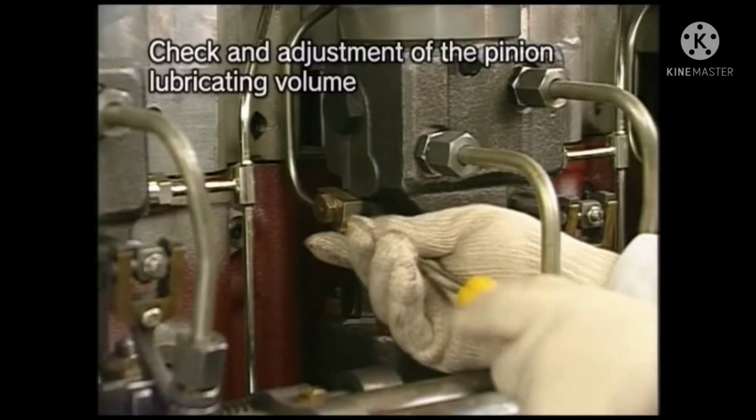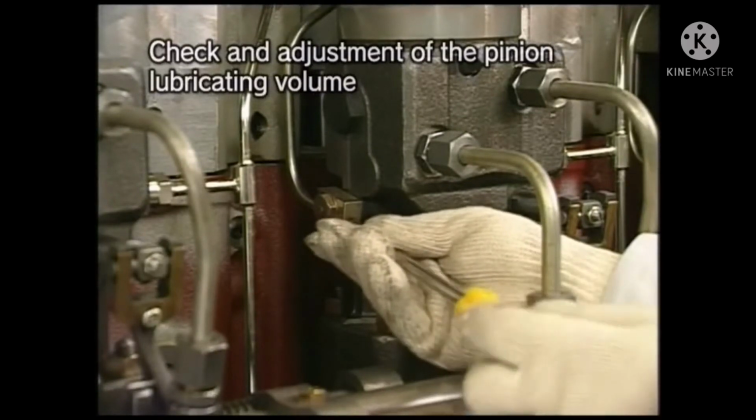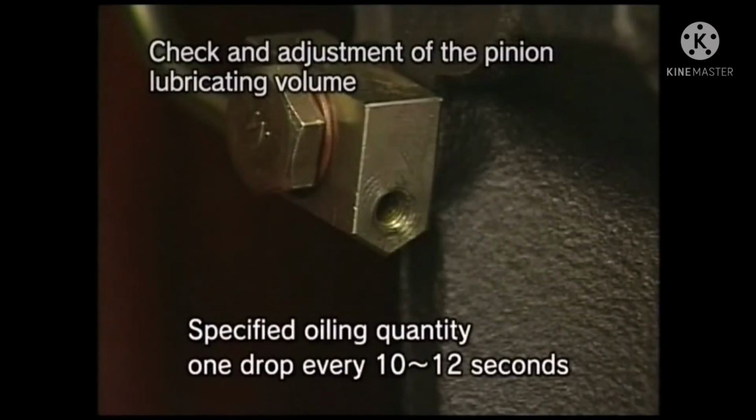Check the oiling quantity by the quantity of the oil dribbling from the plug after removing the plug screw for the check of the drop quantity on the side of the fuel injection pump. Check that the oil drops at the rate of 1 drop every 10 to 12 seconds.